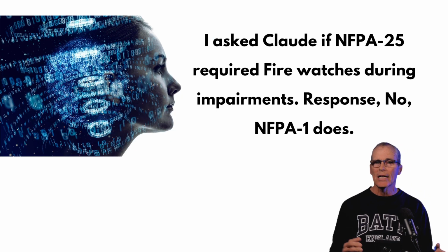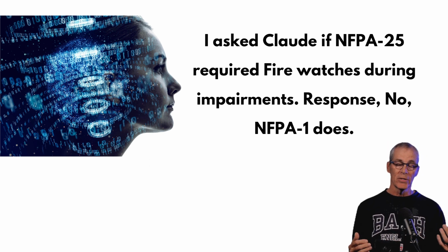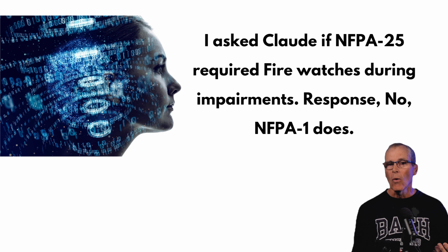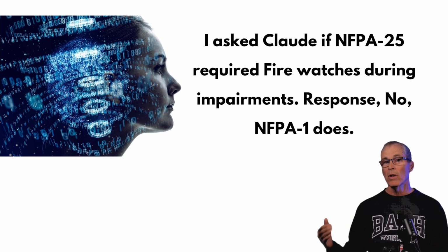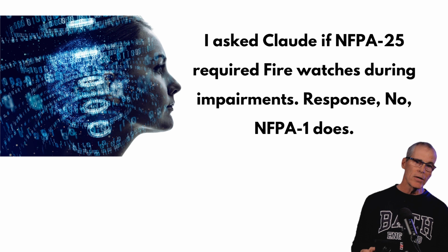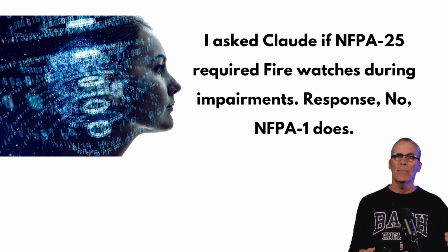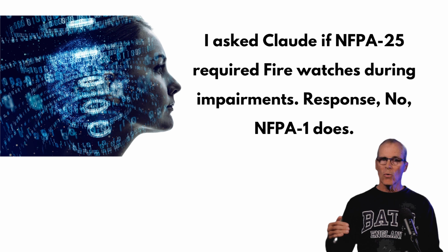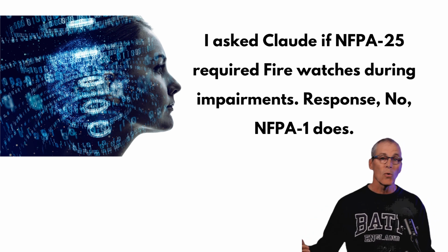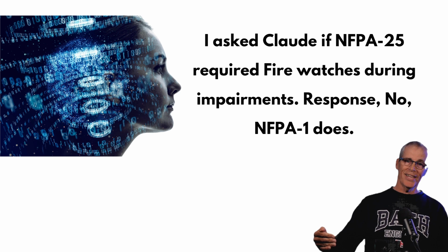All right. I asked Claude if NFPA 25 required fire watches during impairments, and the answer was no. But there was more to the answer, because I was really in an argument over whether NFPA 25 required it. It does definitely have requirements for impairments, but it doesn't require a fire watch, and it doesn't require a member of your structural fire brigade to be your fire watch.